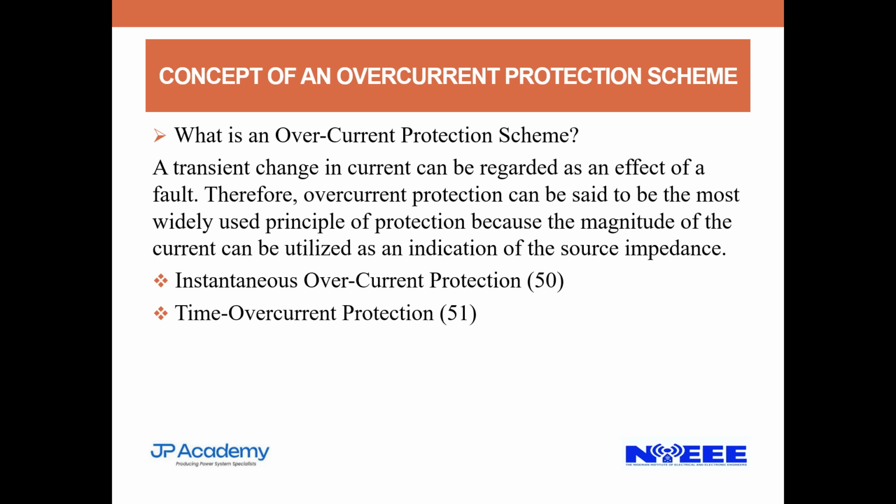So the concept is, we do not put any intentional time delay when it comes to instantaneous protection. But then there is time delay. But when it comes to time overcurrent protection, we actually put intentional time delay.